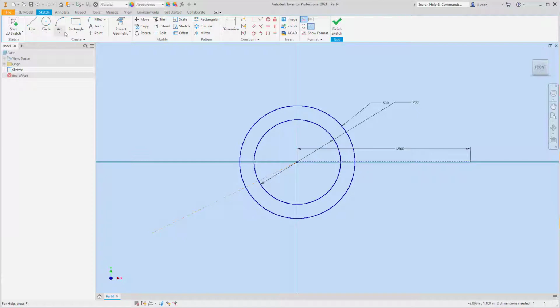So I'm going to pick the line, construction line, pick this line, construction line. And then let me dimension this one. Just going to drag it down. That has, probably should have dimensioned the angle first, but anyway, this is 1.75. Now I'm going to dimension from this line and this line. The angle is 30 degrees here, like so.